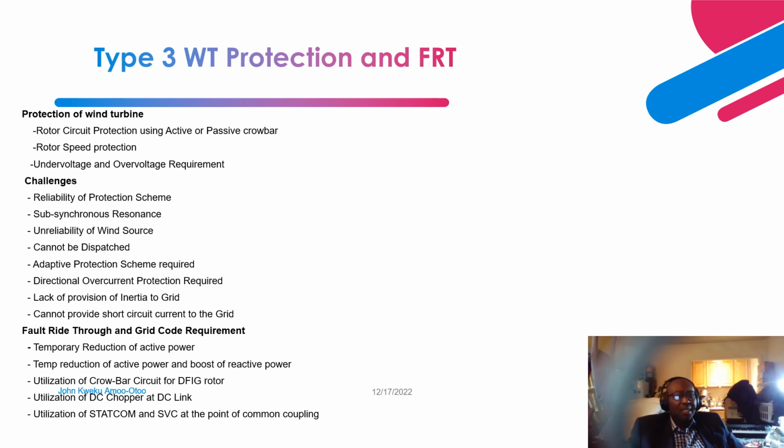On the other hand, these inverter-based power electronics converters do not have that inherent inertia to provide to the grid. As such, when there's a fault, the rate of change of frequency can be very fast, and that itself requires mitigation schemes. There have been virtual inertia initiatives programmed and put into place to provide that virtual inertia to help prevent the fast decrease of the rate of change of frequency.